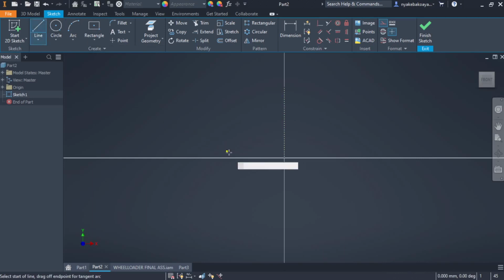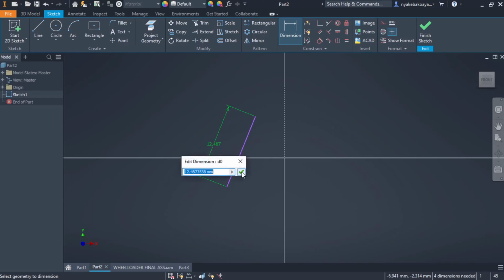And then you can make another line like this, still another construction, but to disable this, let's delete this line. Select line again, but this line you don't want to be a construction line. So to disable that, click again. Now you see this option is deselected. Make another line like that and click OK. Then this line we can even assign dimensions to.